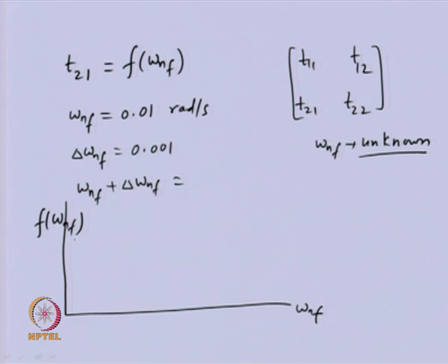because now you can see that when we are assuming some natural frequency, this overall transfer matrix we can get in numerical form, because all the point matrix and field matrix will be known to us, and we need to see just this particular T21 component for the example which we have shown. For different boundary conditions, different components we need to observe. So T21 for the free condition we found as a frequency equation.